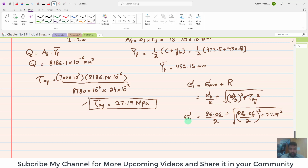This is the principal stress. Clear? So when you calculate this, principal stress comes out to be 93.9 megapascal. So this is the answer of part B, that is to find out the principal stresses at the junction of flange and web.